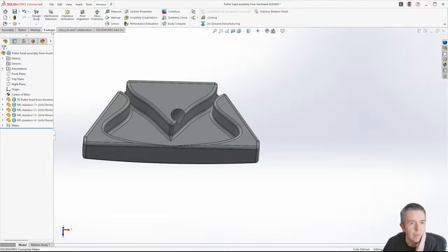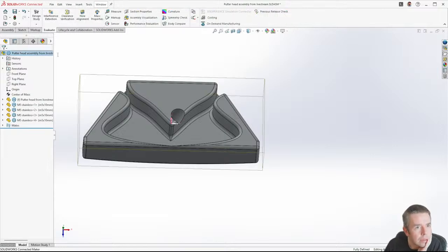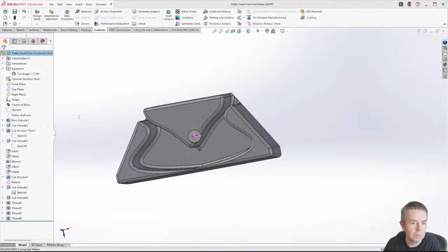So we've got 5290 on the moment of inertia that matters in the rules. And if we go back to just the putter head, we had 5094. I'm just showing you that the scheme to put screws in to move the moment of inertia, to increase the moment of inertia back to where it was before we put the holes to put the screws in, roughly speaking, works.